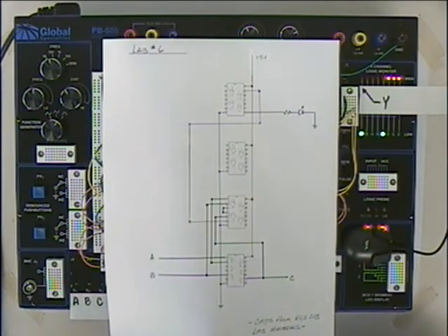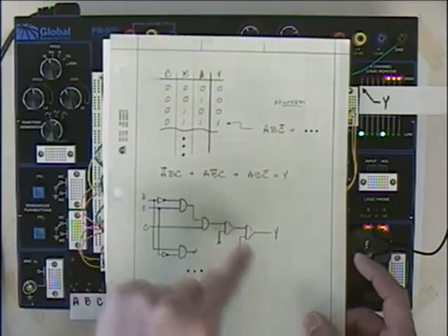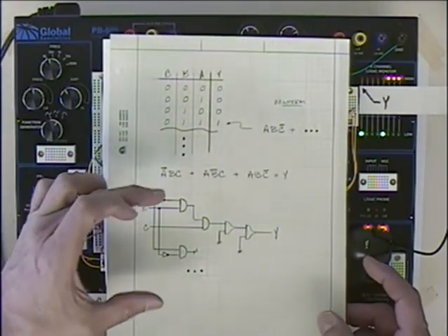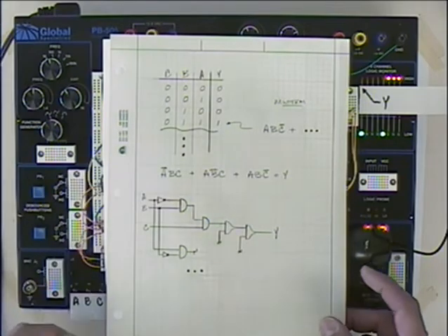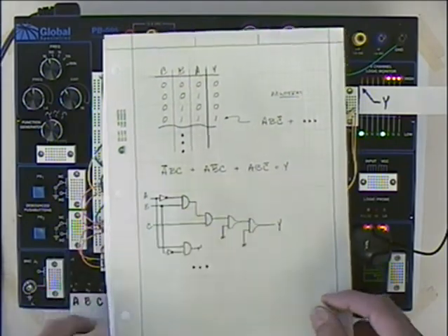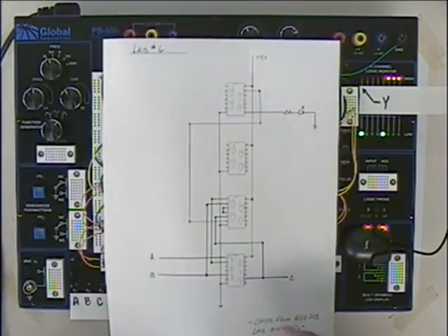The pin number 14, the upper right pin, that's the VCC, the positive 5 volts since we're using TTL. And then again, I could start to hook these together, and I haven't done the entire thing. I've done about as much on this as I did on the circuit diagram. Again, I don't want you just to capture this and call it good enough. I want you to put a little thought into finishing it up. And likewise with this, I don't want you just to capture it. I want you to put a little more thought into finishing it up.